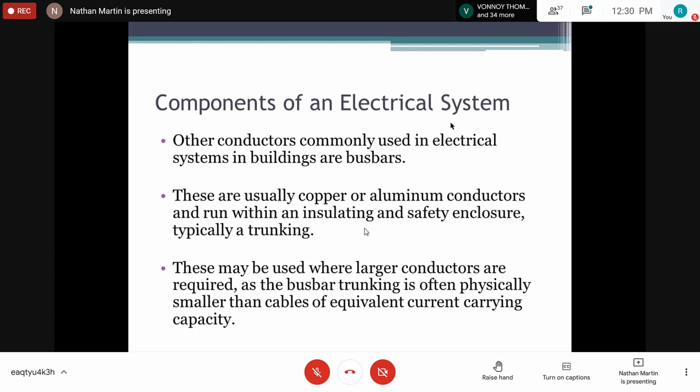Compared to your small commercial or your residence, where you have one meter box and one distribution panel in most houses, you connect from that meter box to your panel box and then from your panel box to the different sub-circuits. Yes, your panel box does have bus bars in it, because those little sprung strips that you connect your breakers onto are also classified as bus bar, right? So you're not going to see a bus bar by itself. To answer your question, you're going to see it in an enclosure.